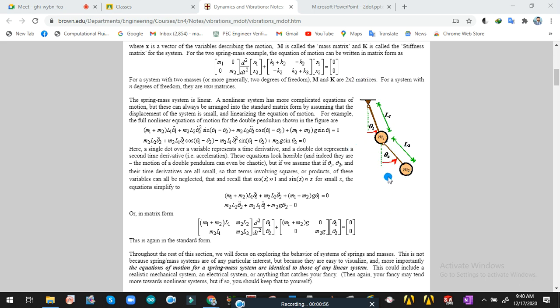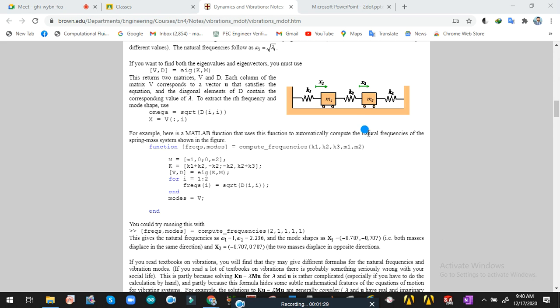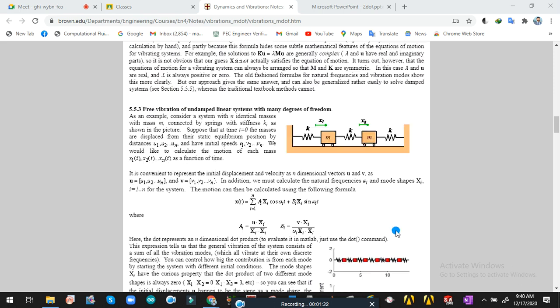So, here in this case what can you say, how many possible masses are there? Number of masses? Two masses, sir. And possible type of motion by each mass? One, sir. Yes, rotational motion only. So you can say 2 multiplied by 1, that is 2. That means this system can withstand 2 degrees of freedom motion. In this case again we will have 2 degrees of freedom.